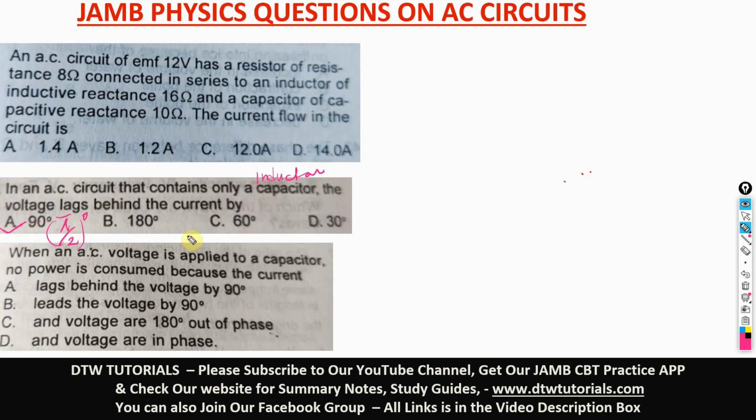It's opposite. So always know that. For a capacitor, voltage lags behind the current. For an inductor, current lags behind the voltage. Now, look at this same question that has been twisted. It's the same thing but twisted again, and it's the same answer.